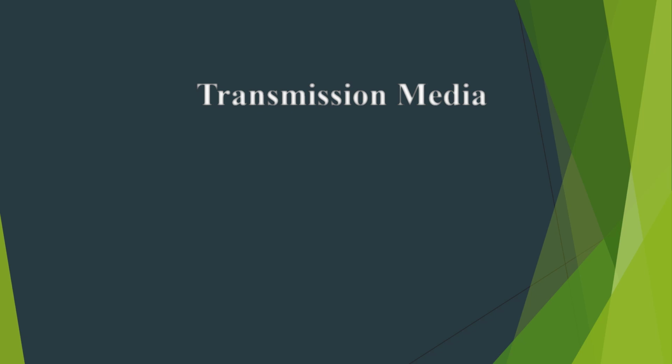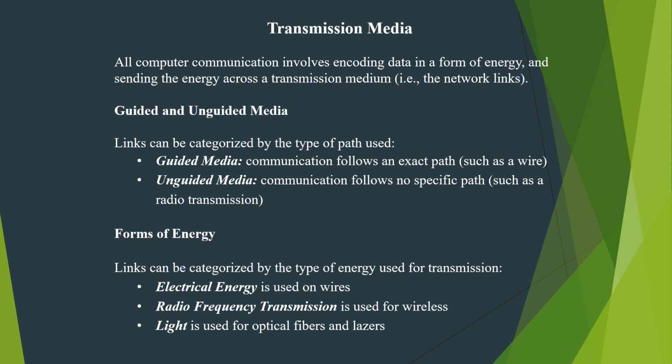Different types of transmission media are used for different data transfer rates and long distances. Bandwidth, noise, radiation, and attenuation are considered while using the different transmission media. Higher bandwidth transmission media support higher data rates. Attenuation limits the usable distance that data can travel on media. Noise is related to electrical signals that can cause distortion of the data signal and data errors. Radiation is the leakage of signal from the media caused by undesirable electrical characteristics of the transmission media.